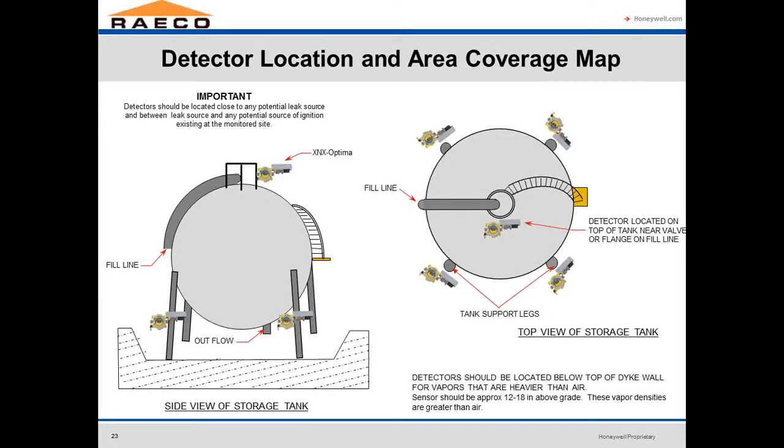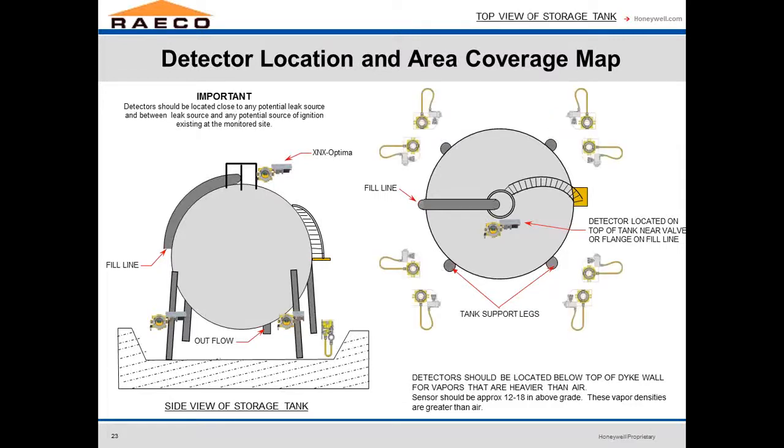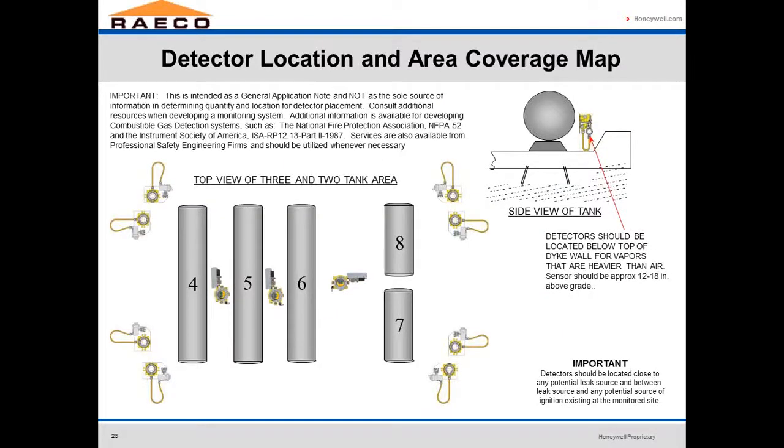The last few slides here, we'll just look at some typical installations in outdoor applications. You see point detection here on some storage bins. The next slide also incorporates some infrared open path detection as well. So we're enhancing not only the sources but also the area around. You can cover a larger area, but you're just looking for more gross releases with open path. Again, just some more applications of using a hybrid type system. We're using both open path and point detection.